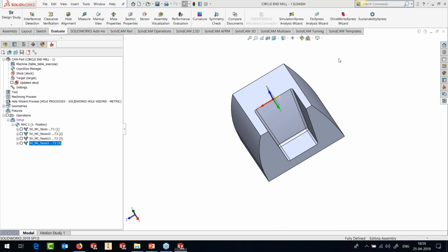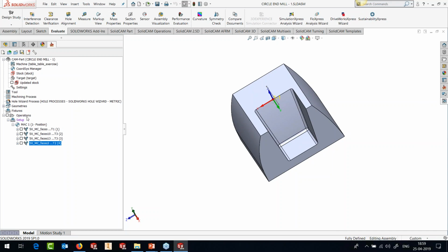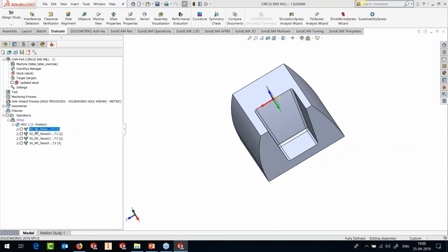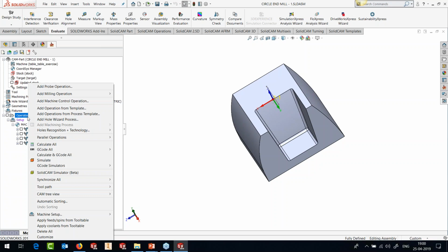If you have, let's open a part. Because what we have in SolidCAM is that you can now straight away pick all your operations, right click on them, and you can go into the mirror functionality. I've just disabled it for this particular setup, but you can just directly mirror, either you can mirror a single toolpath, or you could mirror the entire operations itself. I have just disabled the major mirror here for this particular webinar, because it's a development version that I'm showing you. But you could directly pick the entire project as it is and mirror it straight away.